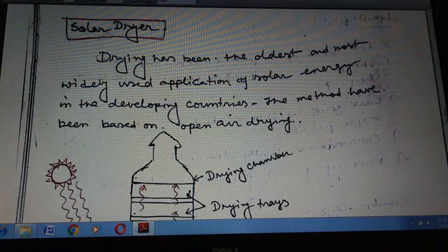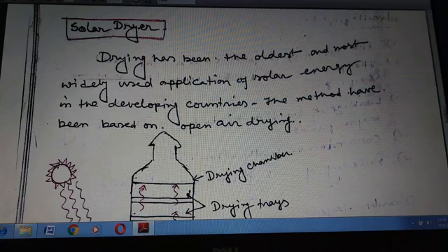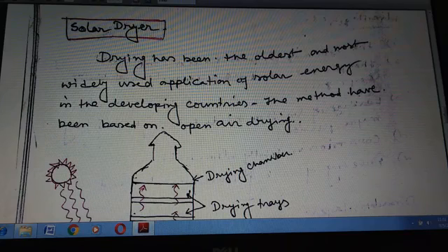The flow of air is often promoted using the stack effect, which takes advantage of the fact that hot air rises and can therefore be drawn upward to the chimney, while drawing in cooler air from below. Alternatively, a fan can also be used in this system.